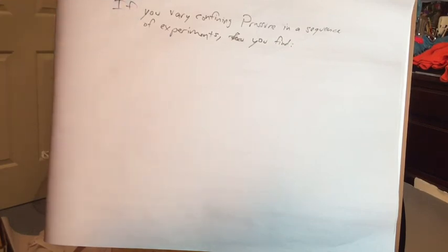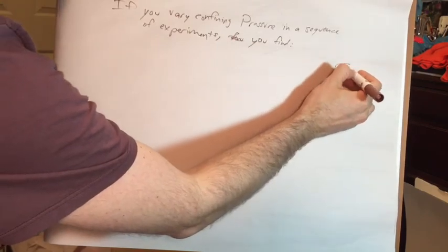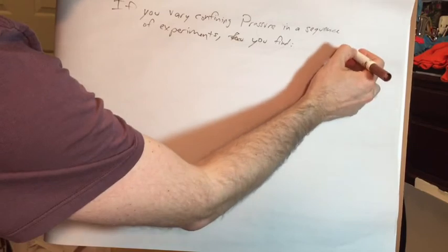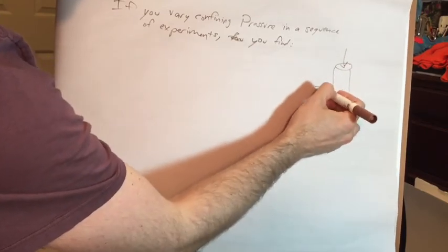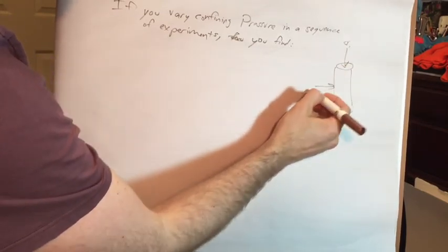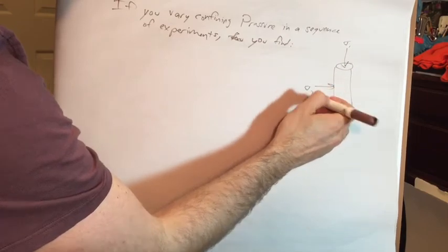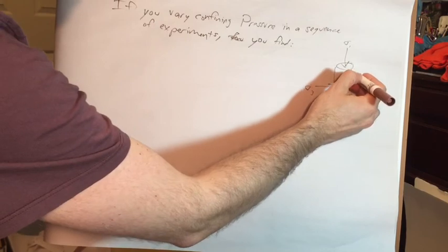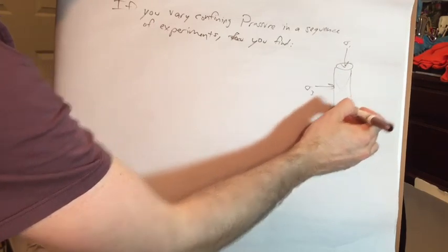Basically, we're talking about taking several cylinders of rock, applying different combinations of sigma 1 and sigma 3 to them until they break.